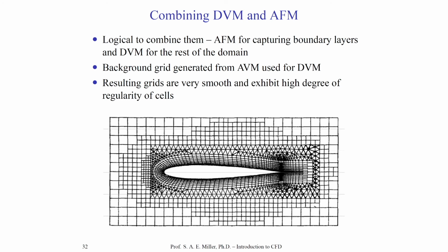This surface might have 10 to 15 advancing fronts or layers. We might call these the number of layers, and the number of steps is about 15, with an initial step of about delta y of, say, 1 times 10 to the negative 8th meters. And each additional step might multiply the delta y from the previous step by, say, 1.1. That is a 10% increase in spacing. These are settings that you can put in computational grid generation programs to tell the advancing front method how far to go into the field.